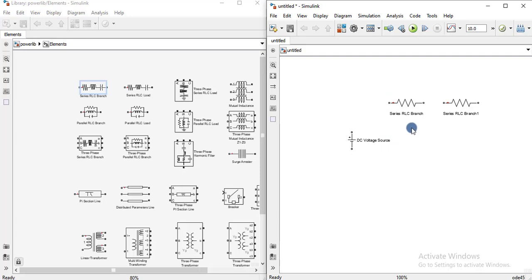Now the third and most effective method for copying an element is to just click on the element, hold the right click, and then drag down. Okay, so you can have multiple branches like this. Just click, then drag, click and then drag. Similarly, to delete an element, just click on it and press the delete button from the keyboard.